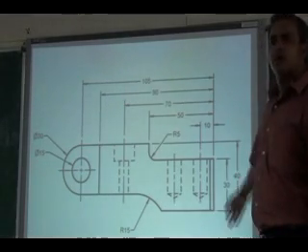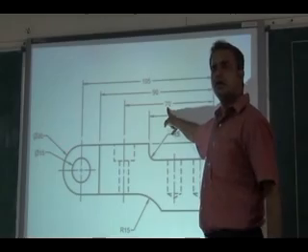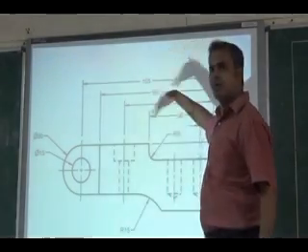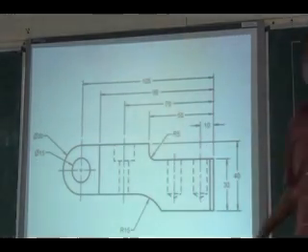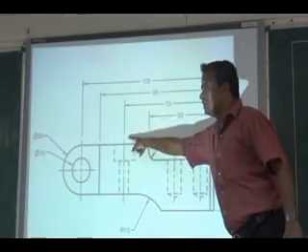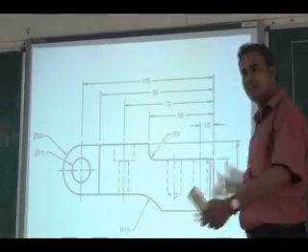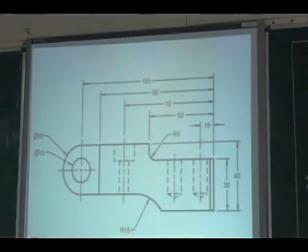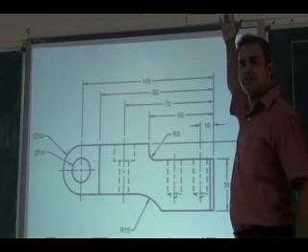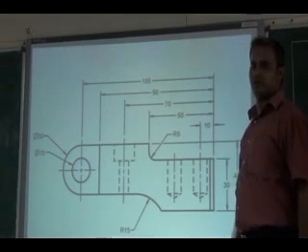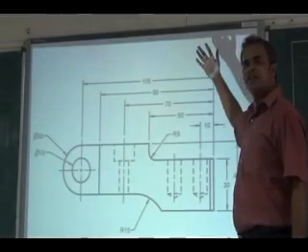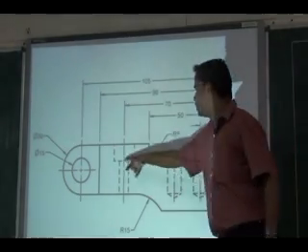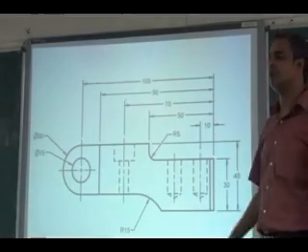No mistake. Then, you see this 17 should be above. What is wrong in this 17? All the dimension values should be above the dimension line, but also the 17 is a dimension for the hidden lines, hidden details. I should not dimension the hidden details. So I can have another view of the same geometry, the same object, where those holes will be visible. There I can show the dimensions. For this view, I have a hidden detail, so you should not dimension it.